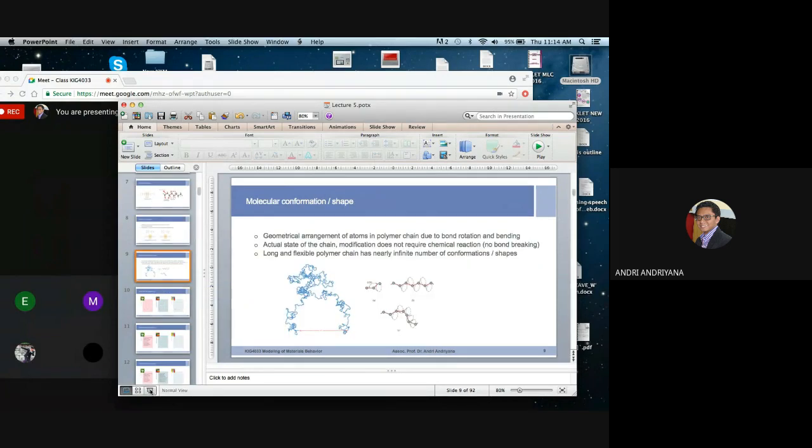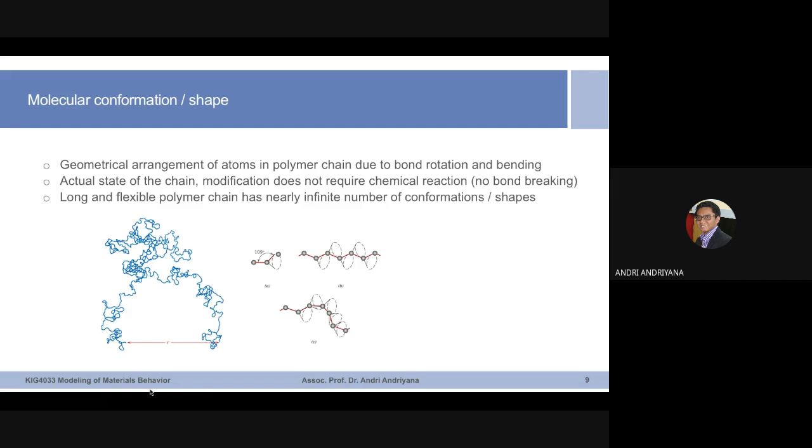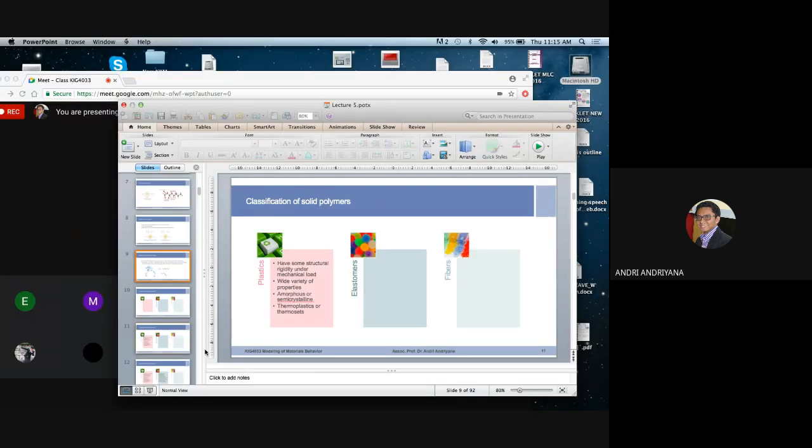This one. So in Gaussian statistical theory, we are focusing on the special situation in which, if this is the conformation or the shape of one single chain, then the distance between one end of the chain to the other end of the chain is much, much smaller than the whole contour length of the polymeric chain. Which means that, from a microscopic standpoint, we only deal with small strain or moderate strain situations. So this is Gaussian statistical theory.